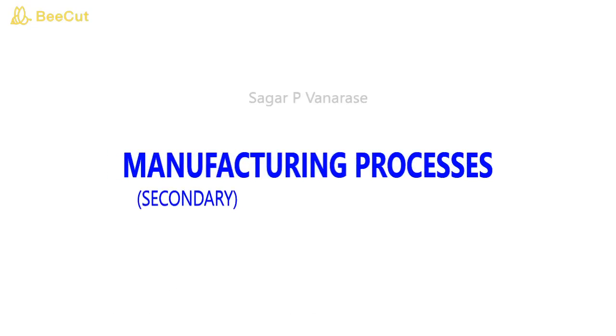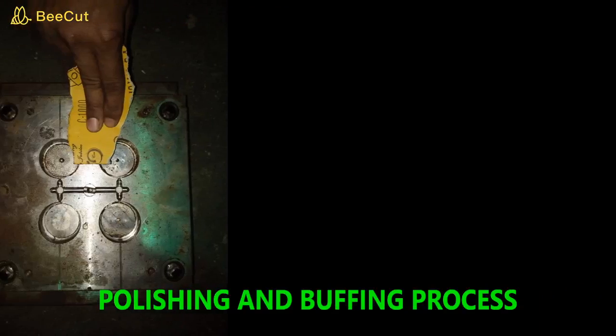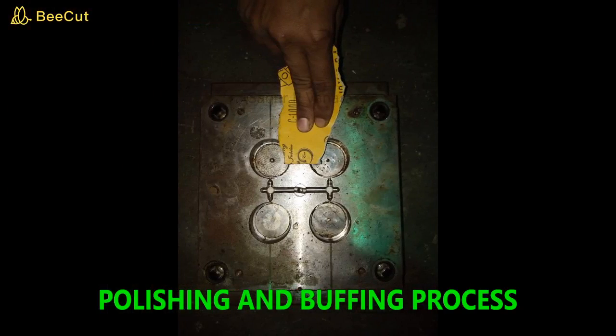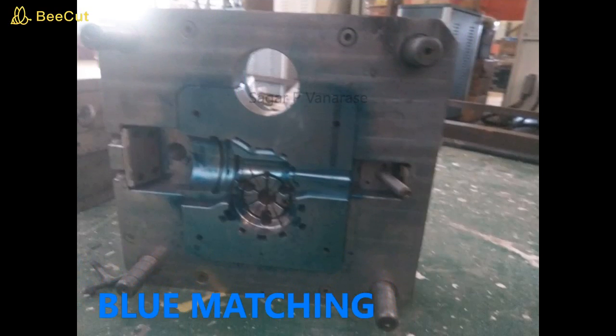The second part of the machining process is secondary machining, in which the mold gets its finishing touch or final touch-up, which includes polishing and buffing of the internal parts of the mold, such as the runner, sprue, gate, and the impression of the mold. Another part of mold making is to match the mold platens to one another. There should be zero gap between the core plate and the cavity plate. This process is known as blue matching.